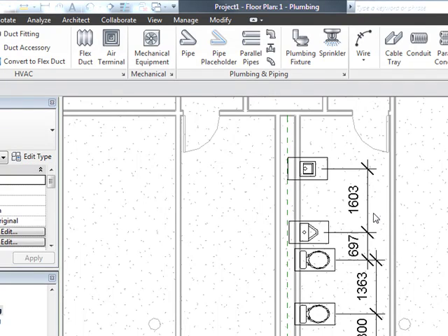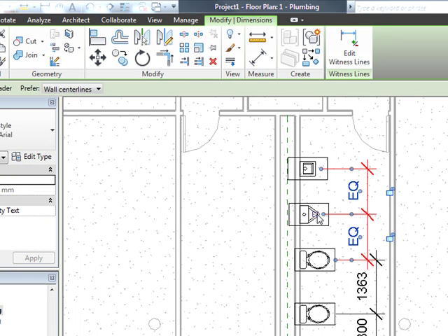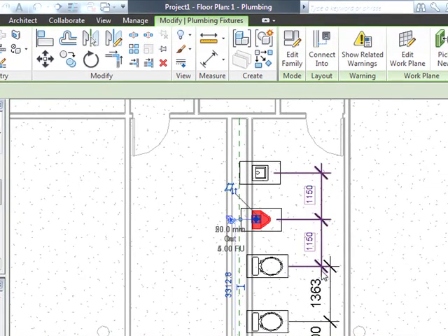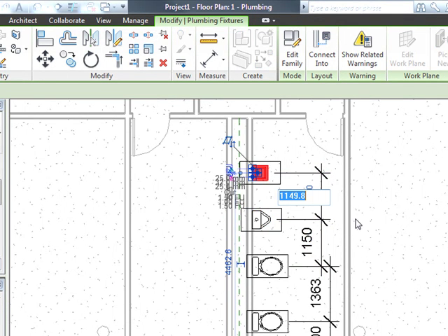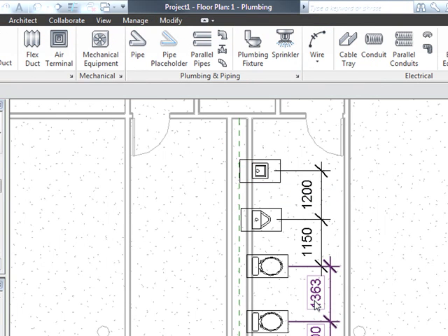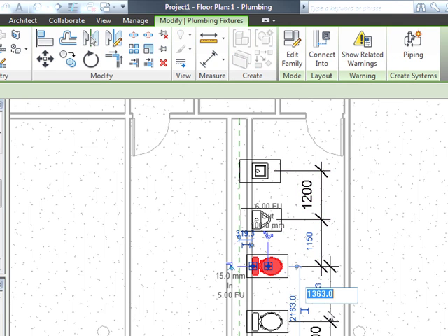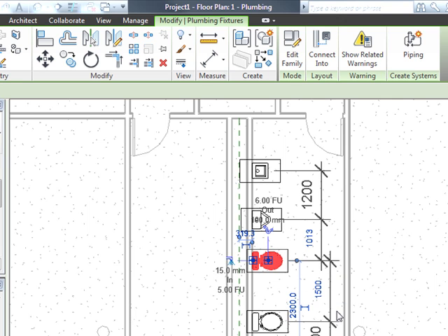For the second one, you might want to make it equal. Okay. Right click, EQ display, and then okay. Click one of the components and you can change the value. Maybe we can put it down as 1200. It's not equal. Okay, the number here is a bit weird. And put it down as 1500.